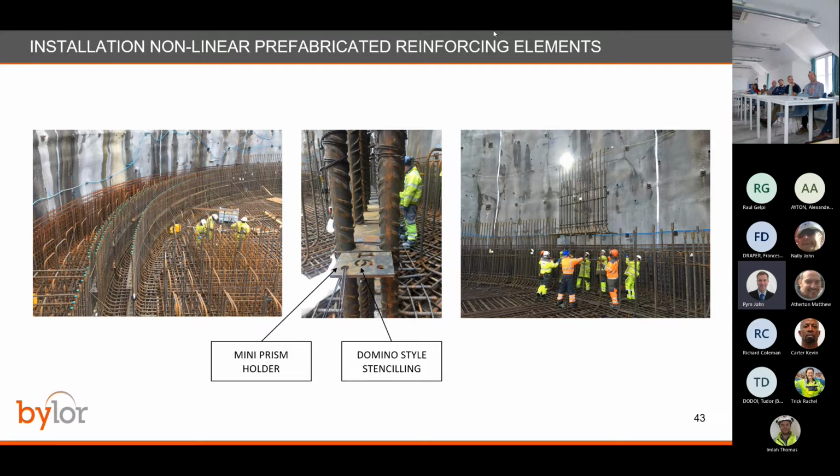So this is what it looks like in practice. We got everything cut, we gave it to the prefabricated reinforcement team. They assembled these prefabricated units, they welded the templates to them, and in the end we were able to lift in 141 linear meters of radial wall in 40 lifts over 2 days with very, very minimal setting out.